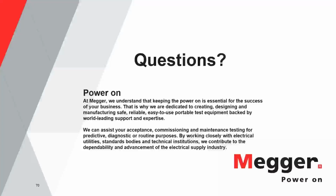So under the experimental side, if you look into the reference provided by IEEE C57.149, which is, I think, one of the best documents given for interpretation of results, you will see that, yes, there are different patterns, and most of them are shown in the way of an end-to-end open circuit or short circuit test, and you can do some sort of analysis. But when things happen in the field, you will see that most of the time it's not just one thing happening. It's not just deformation. It's not just elongation. You may have as well a short circuit in your turns. So keep that in mind.